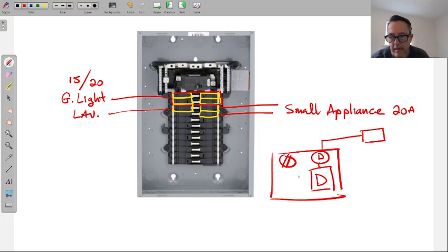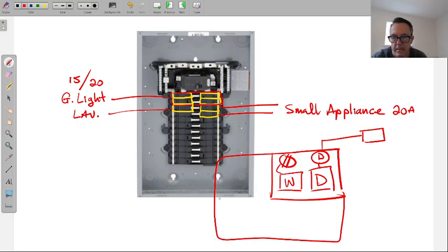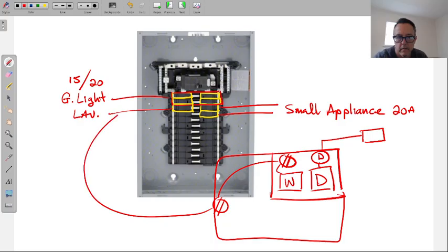Well, if you have an outlet in there, what is the person going to plug into that? The washing machine. If it's a little room and that's all you can fit in there, a washer and a dryer, you don't have to worry about another outlet in there. But if it's a larger laundry room and now potentially the person could bring in something else here, you might want to put another outlet in this room. So 2 outlets for this room.